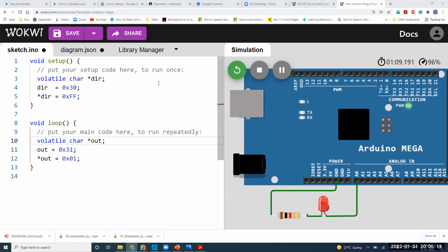But when you do it on embedded, even for the very first program to turn on an LED, you should know volatile. If you use the Arduino library, pinMode or digitalWrite, you will never know about volatile. When you go to any interview, the first question they ask you is about volatile. What is volatile? Every embedded engineer should know that.